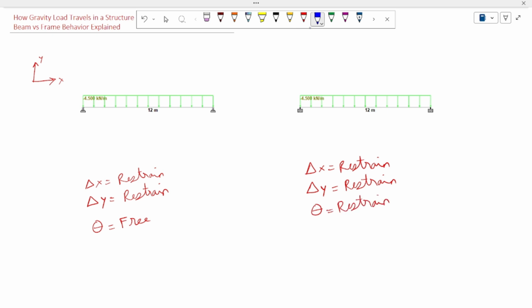You will get this kind of deflection in pinned support connection. In fixed support condition, deflection is different. Here rotation is not allowed towards the support and theta is equal to 0. This is the reason in pinned support connection, moment at supports is 0, but in fixed support condition, moment develops at supports. Let us see this in STAAD Pro.